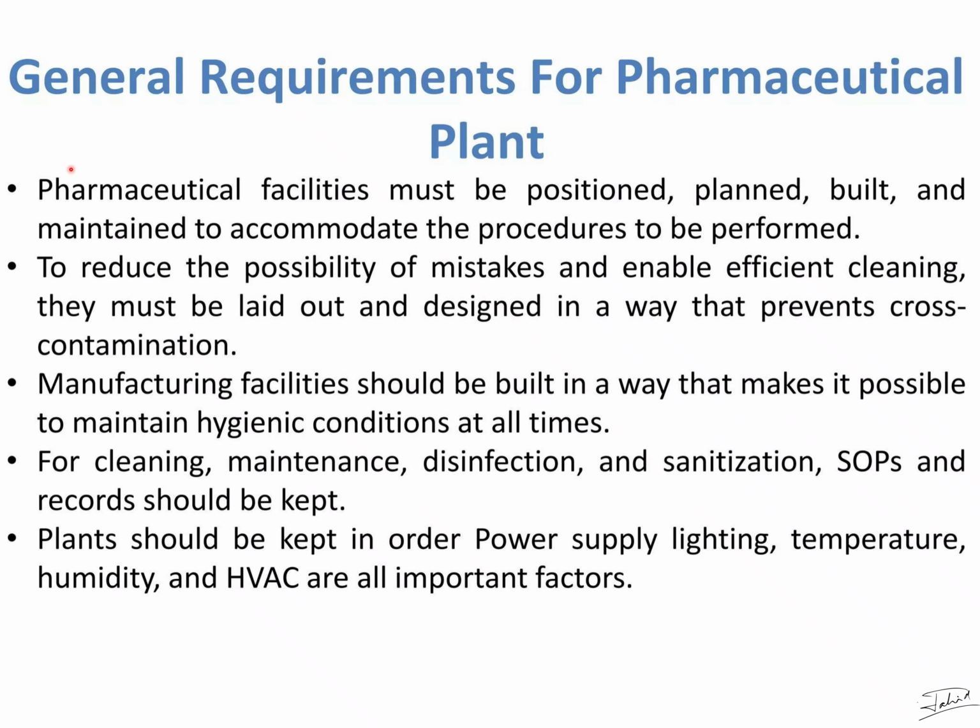So the general requirements for pharmaceutical plant include: pharmaceutical facilities must be positioned, planned, built, and maintained to accommodate the procedure to be performed. So what are the procedures? Procedures are unit operations like mixing, drying, granulation, coating, packaging. Okay. To reduce the possibility of mistakes and enable efficient cleaning, they must be laid out and designed in a